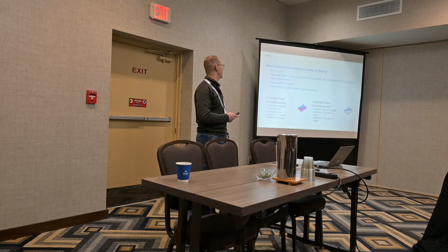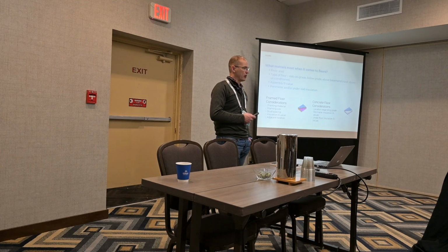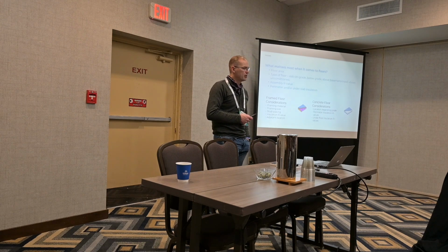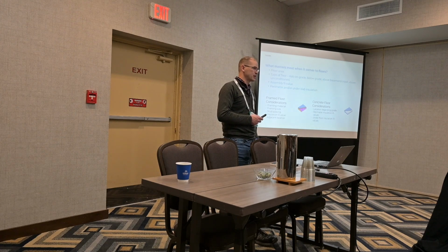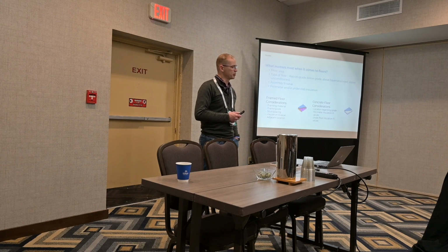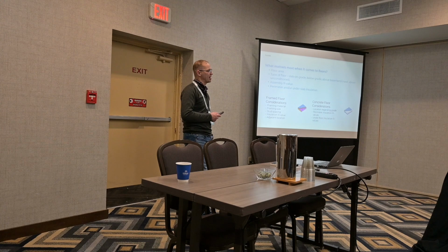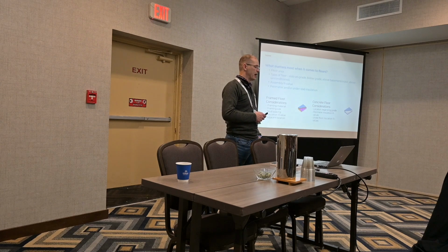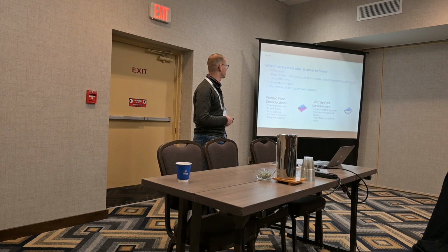So what matters most when it comes to floors? The floor area definitely matters. Make sure you get that correct. Type of floor, whether the home is losing heat or gaining heat through the ground. So that's slab on grade, below grade, above basement, crawl space. If it's an open crawl space, insulated crawl space, things like that, conditioned and unconditioned. The assembly R values on that, perimeter and or the under slab insulation. Under slab insulation may be hard to get without construction details, so you should by all means try to get it, but may not be able to because of that.